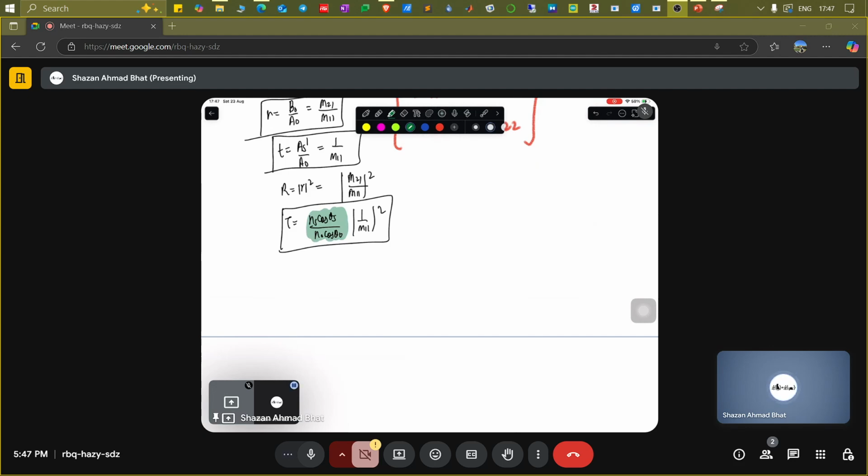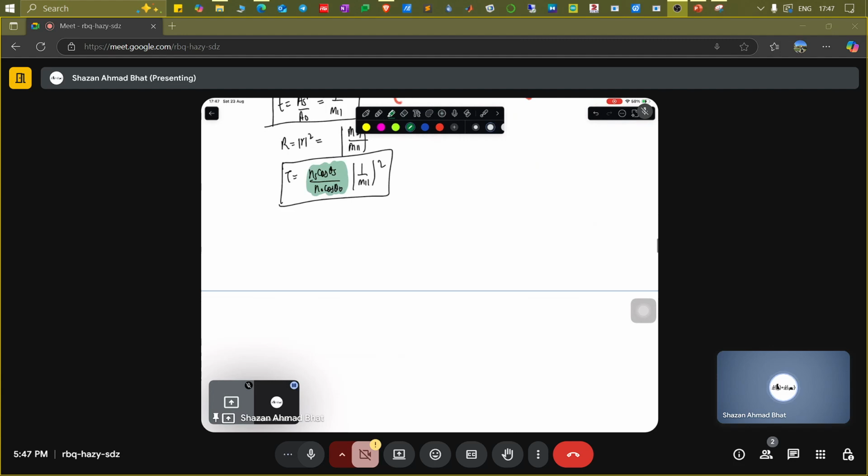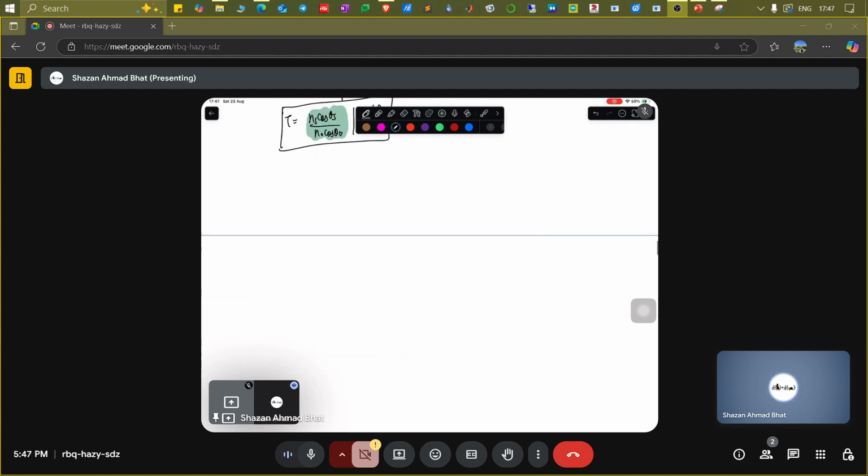Now, why is it important? You can have a structure and determine what the field components are, whether they are reflected or transmitted. You can design certain layers wherein you control how the reflection coefficient and transmission coefficient behave.